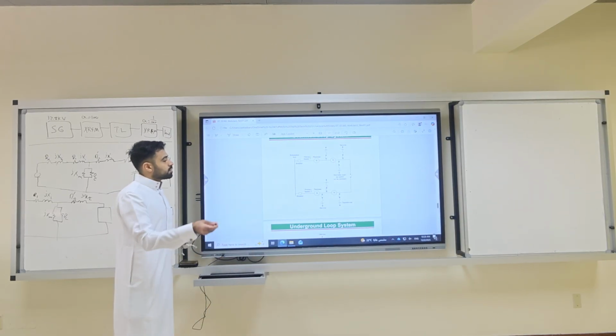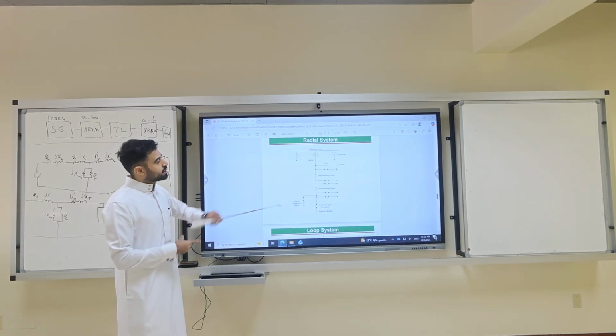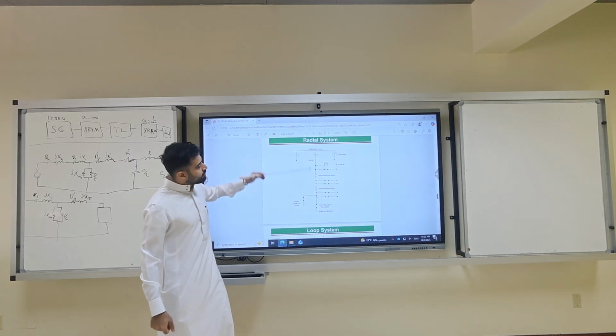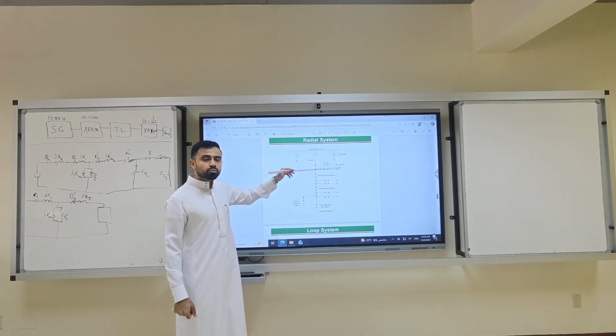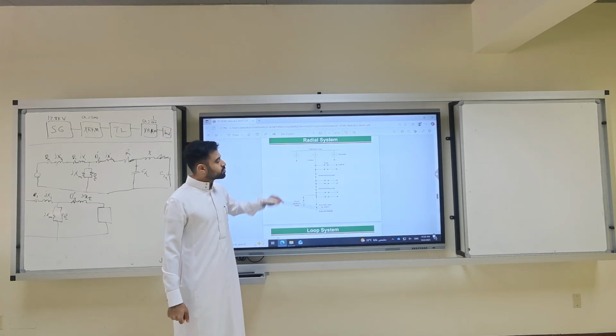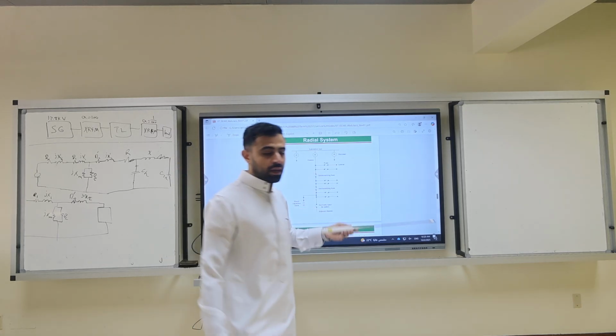Let's continue the discussion about the distribution lines. So, last time we talked about the radial, and in the radial we have lateral phases, A, B, C, whatever, single phase components, because they are used in rural areas mainly.